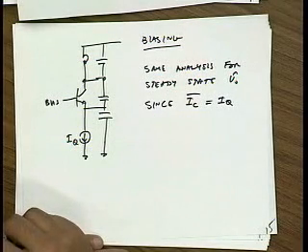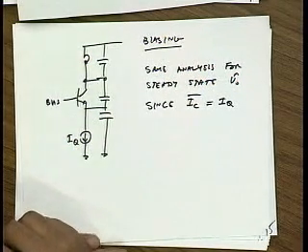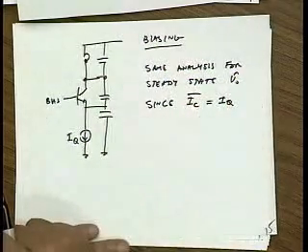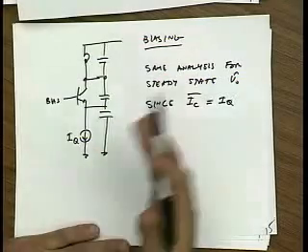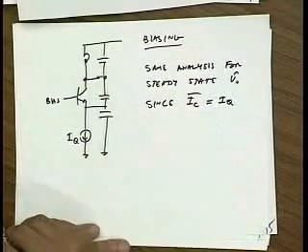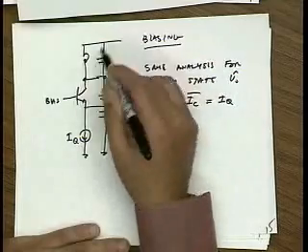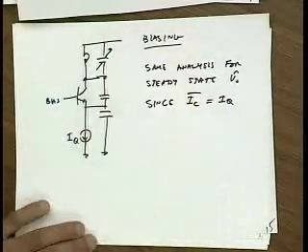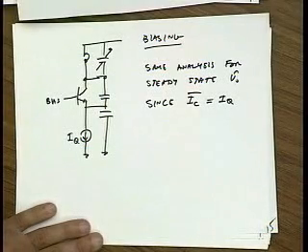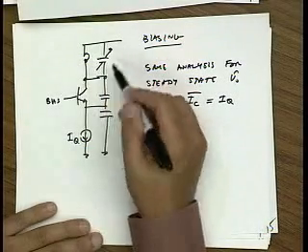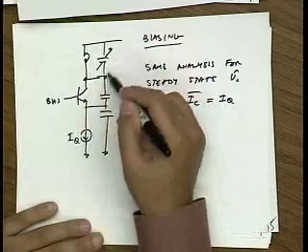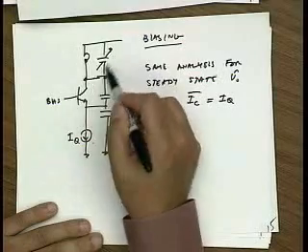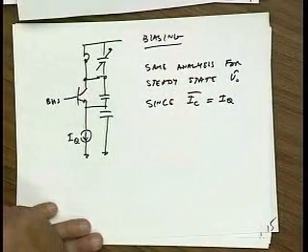You want to avoid using nonlinear capacitors, so you basically want to make these capacitors simple metal capacitors in order to, as we'll see, phase noise is very sensitive to nonlinear capacitors. Unfortunately, if you want to make a VCO, voltage controlled oscillator, you will have to make this a varactor, right? So this would be a PN junction varactor, and we'll talk more about VCOs later, about how to make sure that there is no noise injection from this port. Okay.